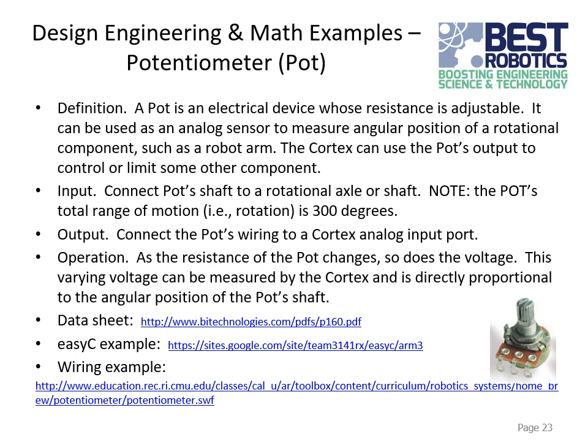So that can be useful if you want to put in software limits of where it turns to. You can keep it from turning beyond a certain point just by reading that potentiometer. You can have the software cut the motors off if it goes too far.